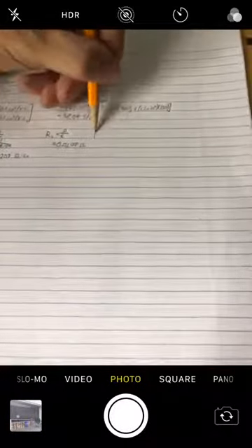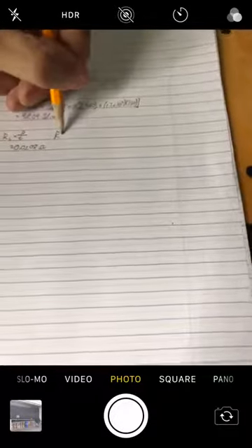But now if we're going to find the total resistance of our diffused layer, we have to consider the length-to-width ratio and multiply it by our sheet resistance. Length over width is simply 10. So 10 times 0.0208, we have a resistance of about 0.208 ohms.